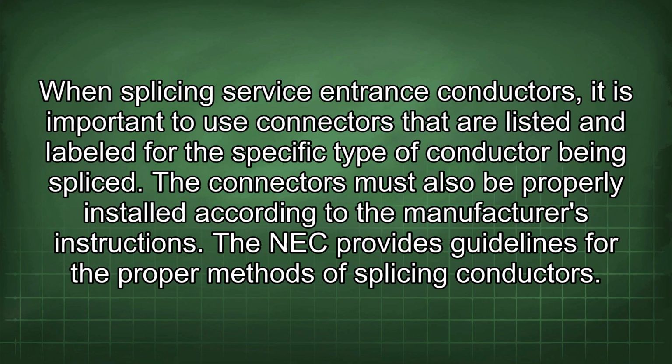When splicing service entrance conductors, it is important to use connectors that are listed and labeled for the specific type of conductor being spliced. The connectors must also be properly installed according to the manufacturer's instructions. The NEC provides guidelines for the proper methods of splicing conductors.